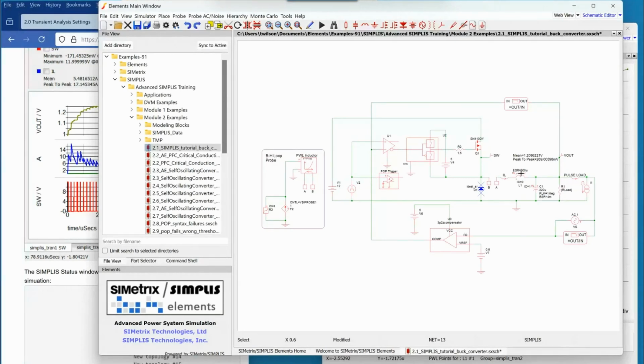And so, yes, you want to reduce the number of piecewise linear segments as much as possible, but still get the required accuracy. Like, Christoph, in your example yesterday, where you're using piecewise linear resistors to generate a multiplier, more piecewise linear segments gives you more accuracy, in terms of just the pure multiplier function.